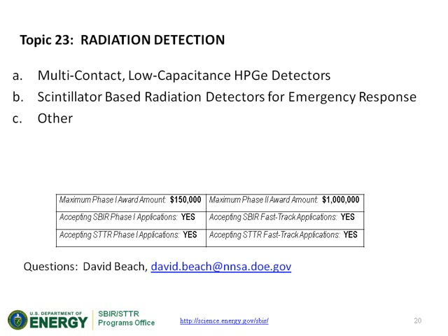But it does talk a little bit further down in the paragraph under 23A. It talks about the high rates requiring short shaping time, so that the short shaping time will interfere with your resolution. It'll degrade the resolution. So ideally you have to design the detector for the shorter shaping time. So that's discussed there. So again, ideally we would like to keep the resolution about the same.